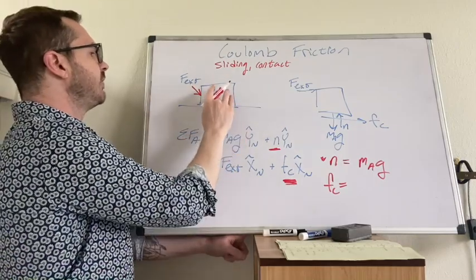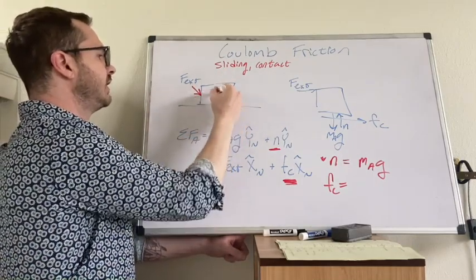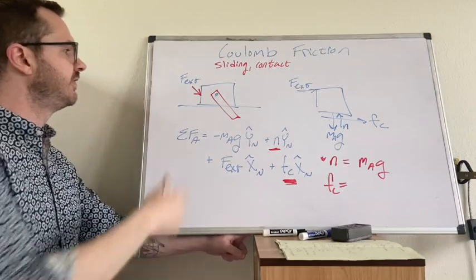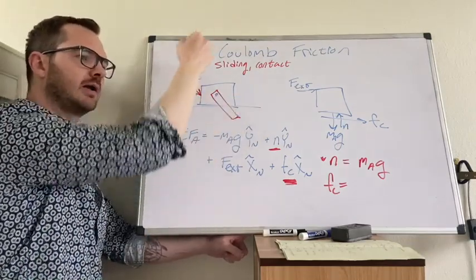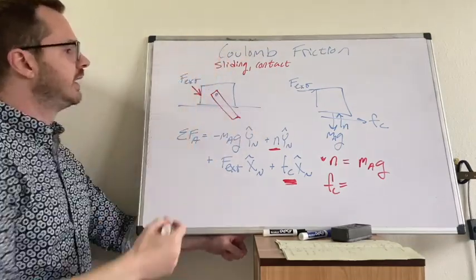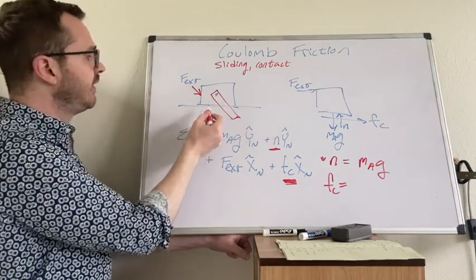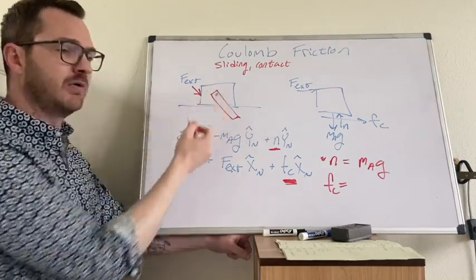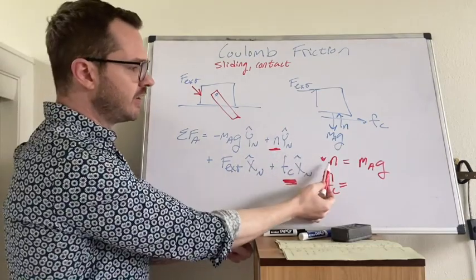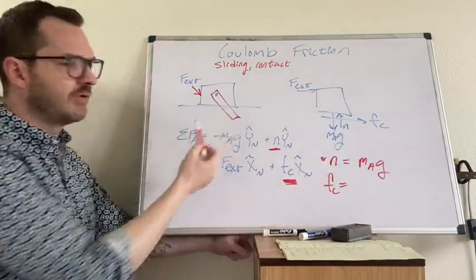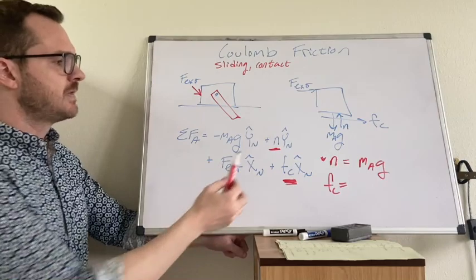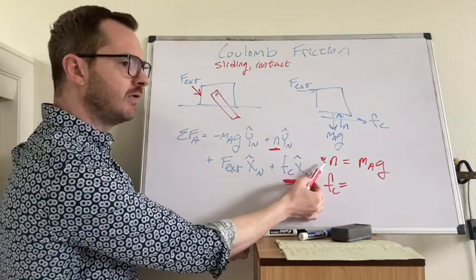We could do something else. We could attach a pendulum to this, and this pendulum could swing, right? It could swing round in a circle. And then there's going to be reaction forces at that pin joint. Those reaction forces are going to have a component in the x and y direction. And then your normal force has to cancel those reaction forces as well. So this is not always true, okay?